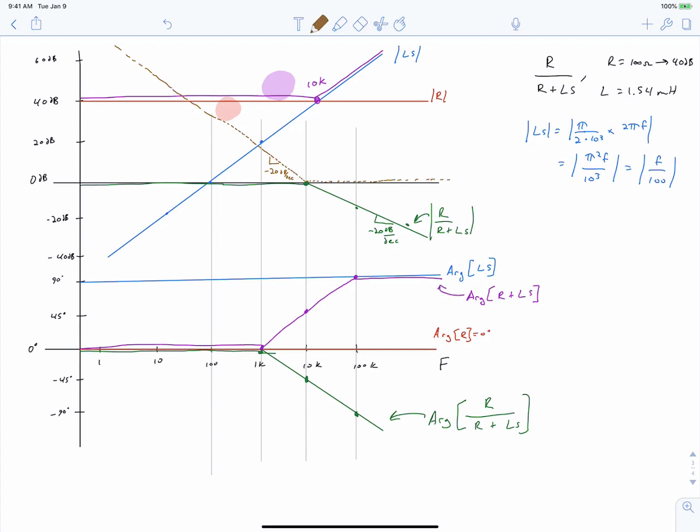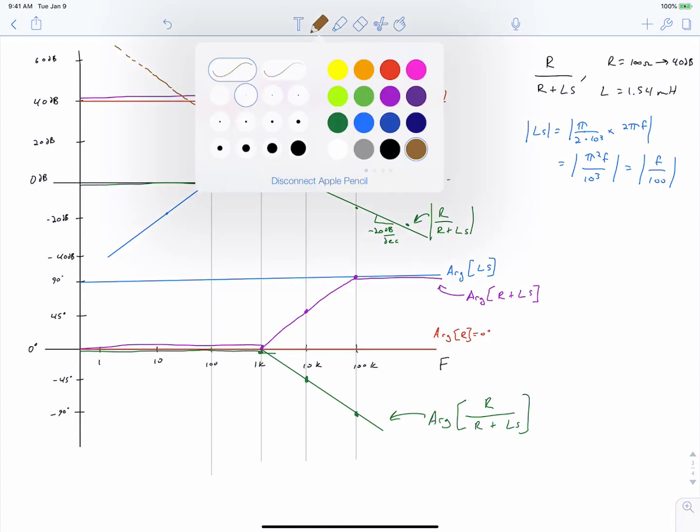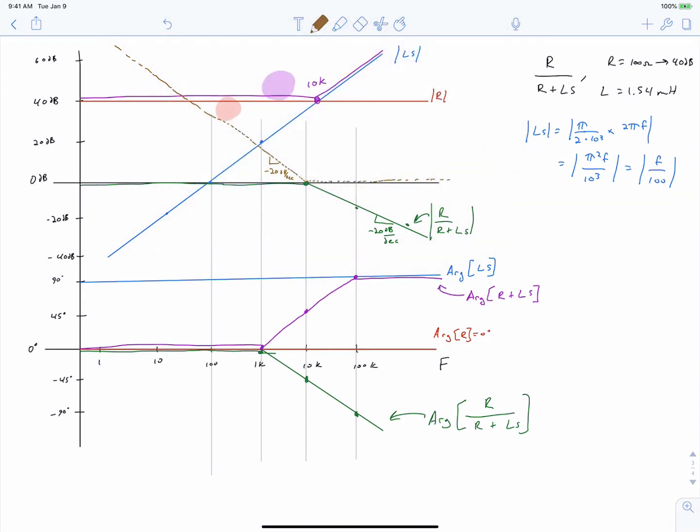And so what is this transfer function composed of? This fictitious transfer function that slopes down at negative 20 decibels per decade and then goes off to infinity with a flat gain. Well, we can view it as being the addition of two terms. One term that's going off at negative 20 decibels per decade and has a gain of 1 when we get to 10 kilohertz.